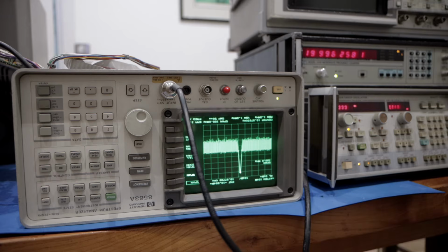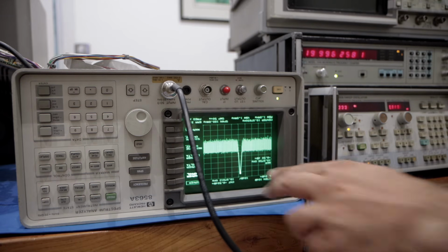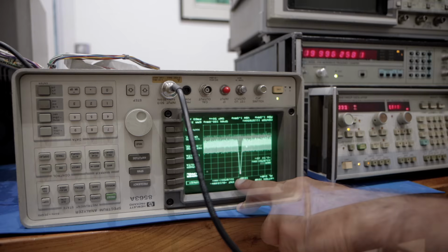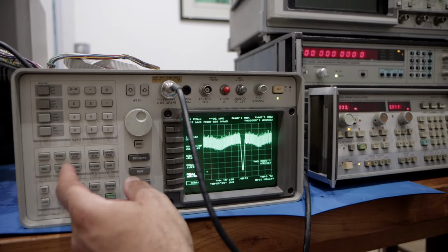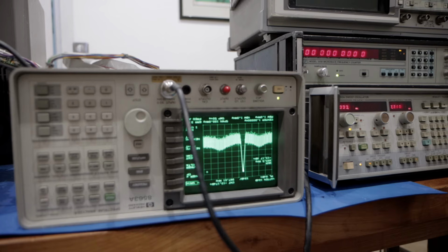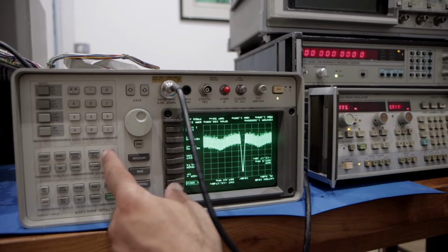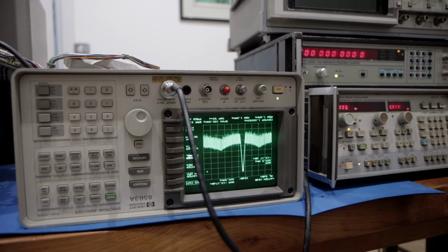Now I'm playing around with it. The first thing I noticed is the level. It's about 10 dB lower than expected. Testing at 1 GHz now. The weird shape of the signal is due to my faulty signal generator, where the first band, 10 MHz to 2.7 GHz, is unreliable. So I can't tell if the amplitude is accurate without my power meter, but I'll save that for later. But still, I'm happy. This project is finally moving in the right direction.